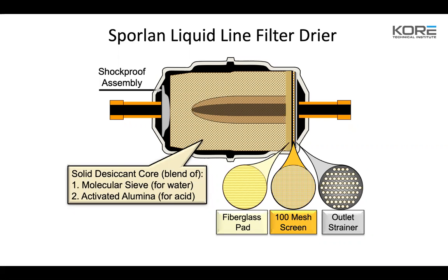Does anybody know off the top of their head the pressure drop across the dryer before you condemn it for Sporlan? Is it 3? 3 is actually high. I mean, you're close. It's 2. So yeah, 2 PSI. So at 3 degrees temperature, if you've got clamps and you can tell, the hard thing